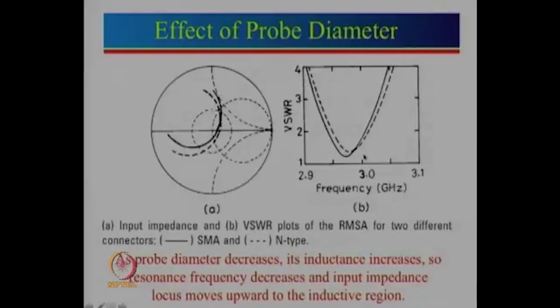Also, there is a small change in the resonance frequency. Why? Because if inductance is increased, then the resonance frequency will decrease slightly. Again, why? Because omega 0 is given by 1 by square root LC. So, if L increases, that means the resonance frequency will decrease.